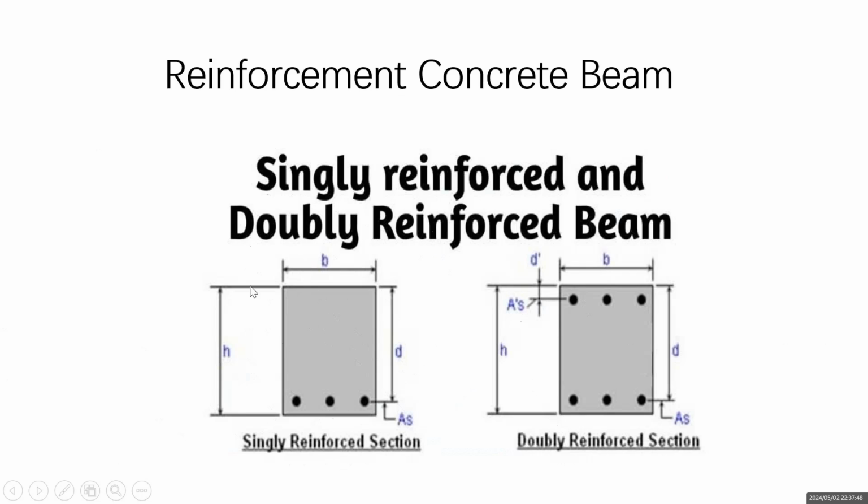So B is the width of the concrete beam. H represents the height of the concrete beam, and these three black dots can change; there can be two, or one. They represent the steel bars, and As here is the cross-sectional area of this reinforcement.